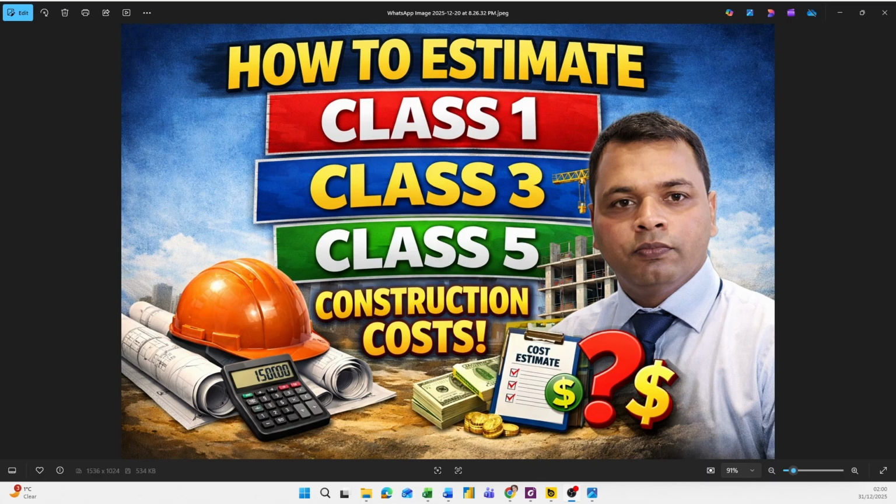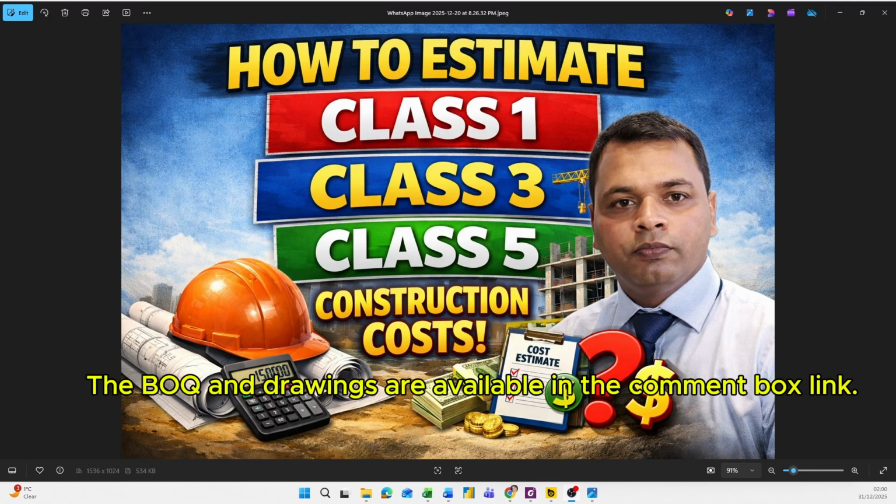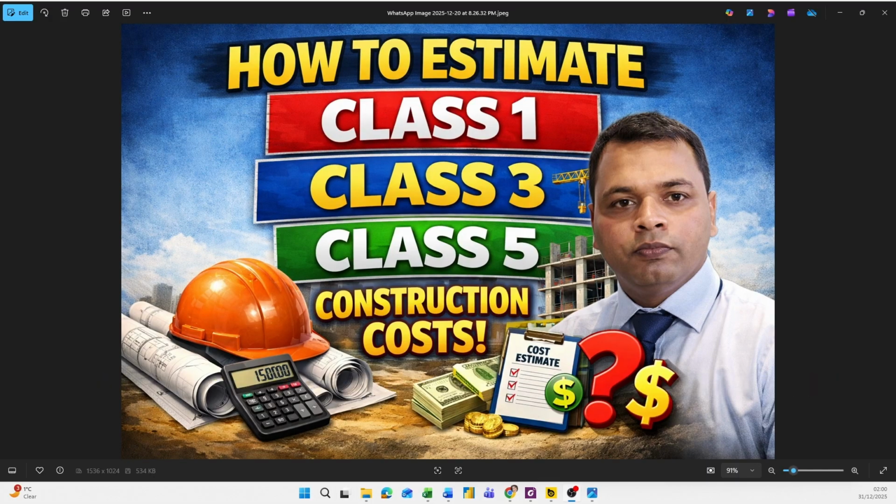Finally, we can see that an estimate fully depends on clear drawings and detailed specifications. If the drawing and specification are well prepared, the estimator can produce the best and most accurate estimate. An estimator always follows the design and specification. If something is unclear or missing, then that item may also be missing from the estimate. That is why, as an estimator, we must ask the design team whenever we have doubt or find missing information. This helps us prepare a complete estimate with fewer missing items and better cost.